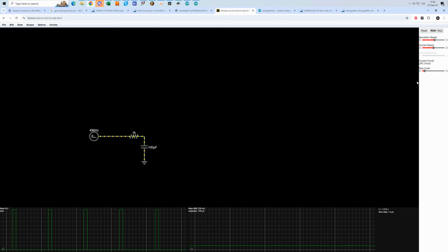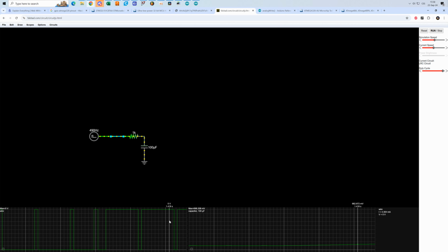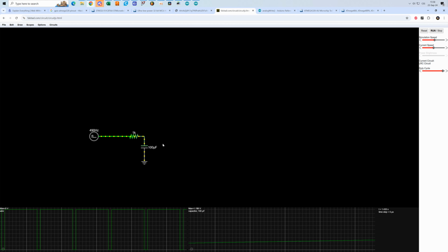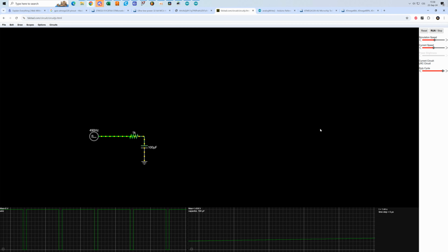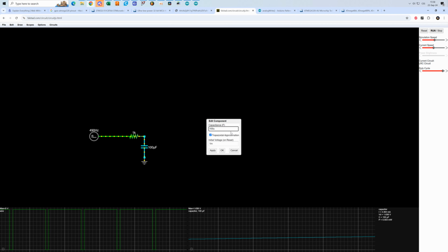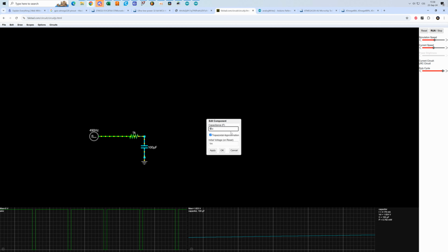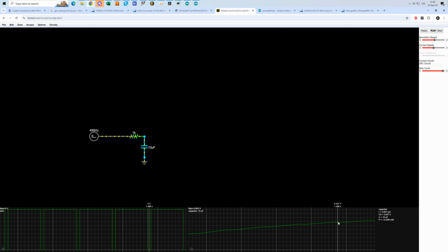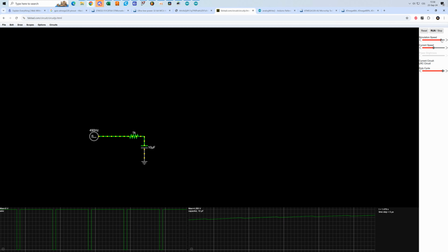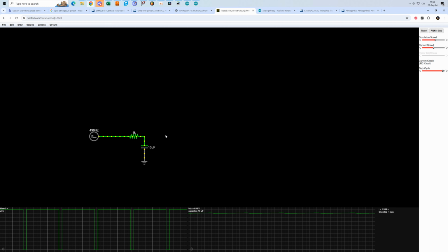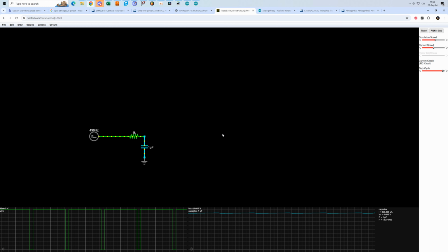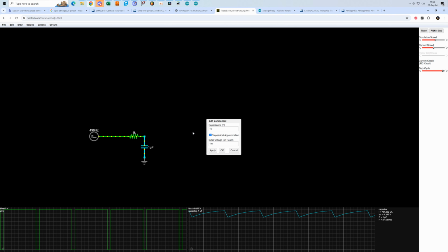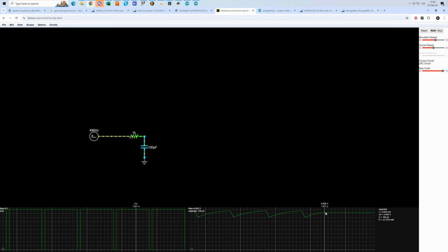So we can change the duty cycle drastically, but it will take some time before this capacitor tells us the correct average. Of course, we could lower the capacitance so that the circuit acts quicker, but then you can see that we have this slight ripple voltage on the capacitor. So if we make it even lower, we can see it even clearer that there is this voltage ripple. So the capacitor needs to be as big as possible so that the voltage is nice and smooth.